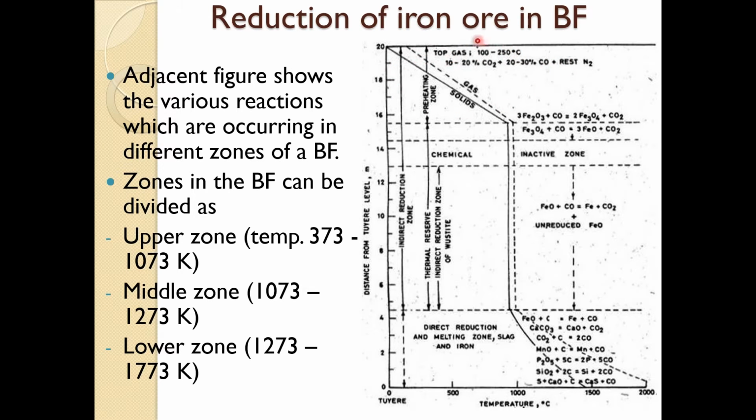In this region the top gas temperature is 250, but really it goes from about 800 down to 250. In this region most of your water gets evaporated, both free moisture and chemically bonded moisture, and some of the reactions you will see in the other slide.